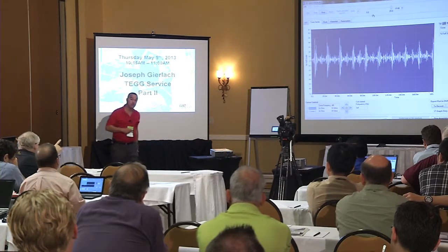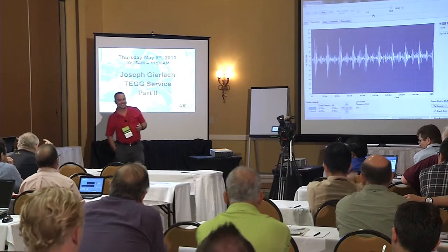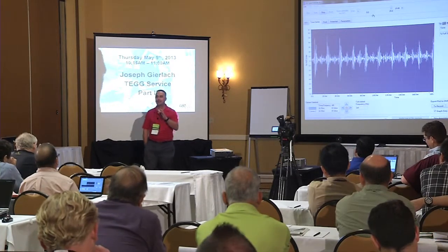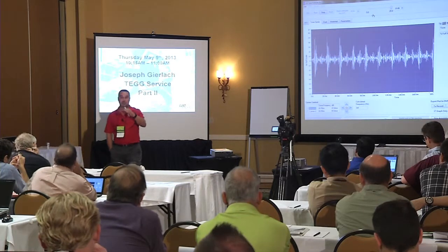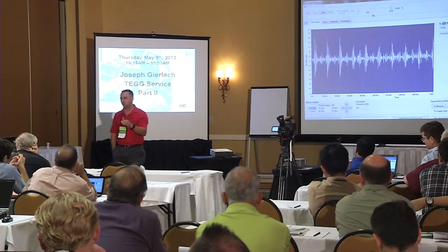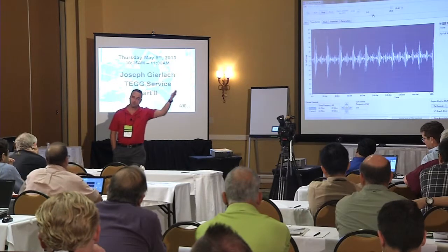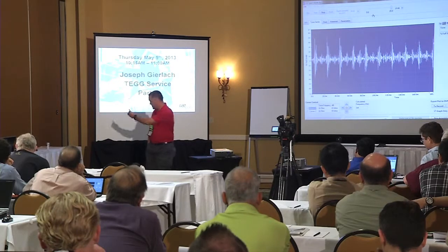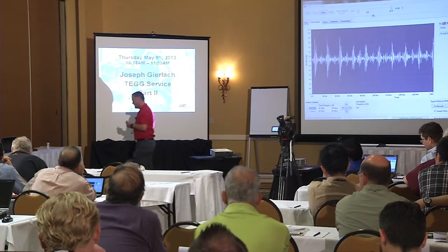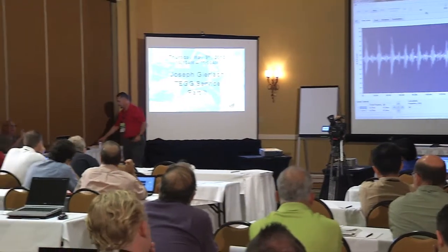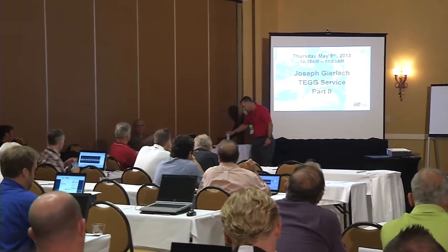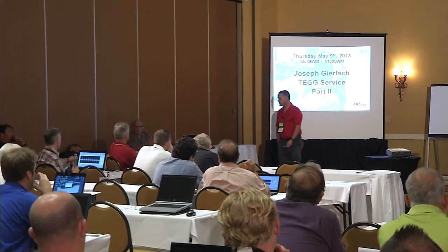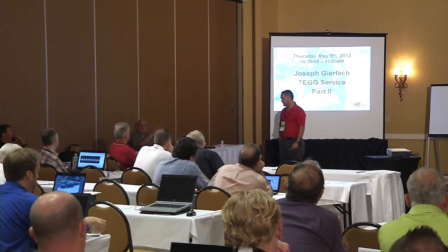Do you have any problems with variable frequency drives, harmonics and those or something like that? The question was about variable speed drives, and do the harmonics produced by drives show up here? I haven't really seen it on this analyzer. But if it's a dry transformer driven by a variable frequency drive, you'd better pay attention to the frequency of the drive and make sure the harmonics of that, whether it's 42 or 40 or whatever, is what you use as your basis.